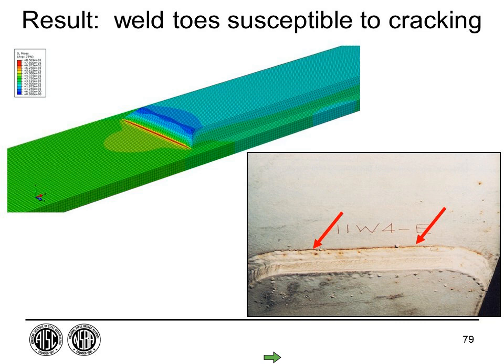So, what does that mean when we're all done here? Weld toes are generally what we worry about. I have high geometric stress concentration, so this would be a cover plate, say on a girder. Sometimes you'll look up when you're traveling under an older bridge and you see a cover plate added to add section modulus, and then it terminates abruptly.